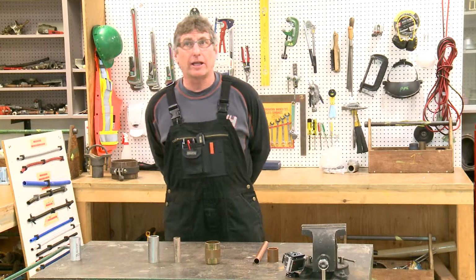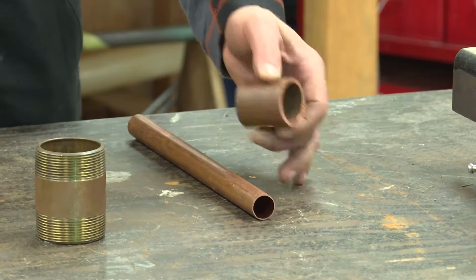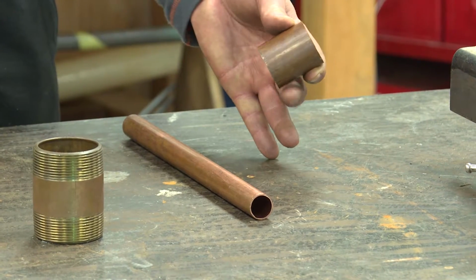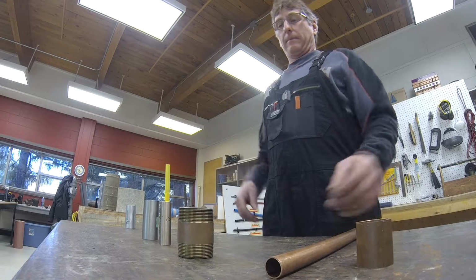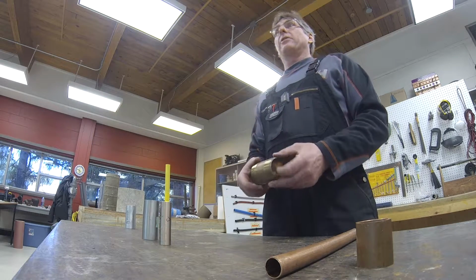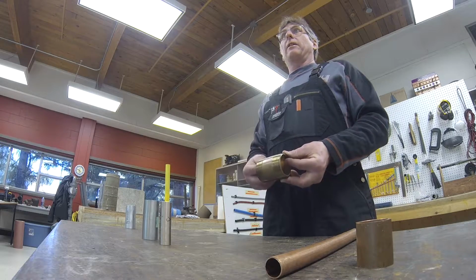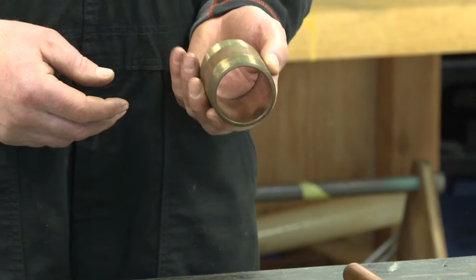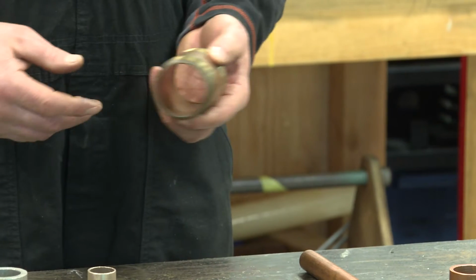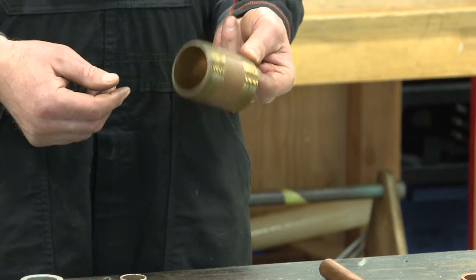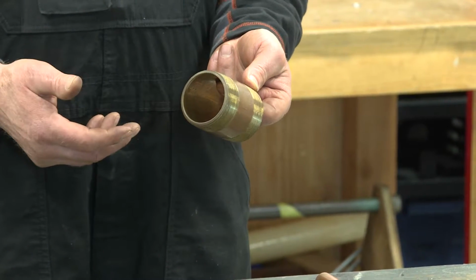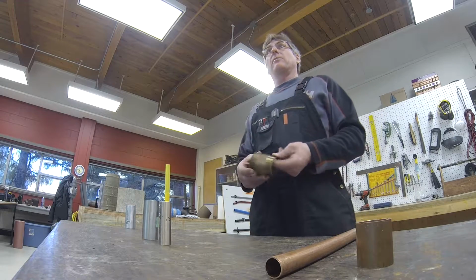In the copper alloy category, we have copper pipe and tube, which are not alloys as they're almost entirely 100% pure copper. Brass, on the other hand, is an alloy composed of copper and zinc. Brass pipe is also called red brass because its primary element is about 85% copper. It has excellent corrosion resistance for potable and non-potable water systems, boiler water, and other similar applications.